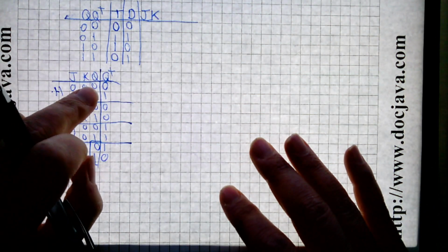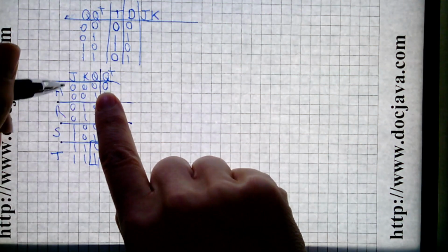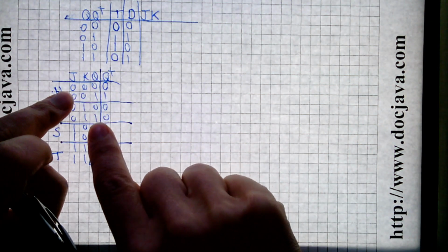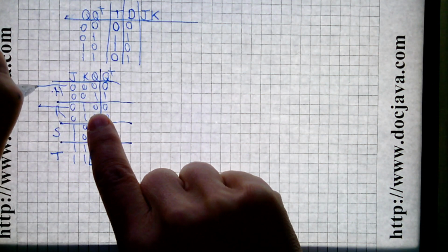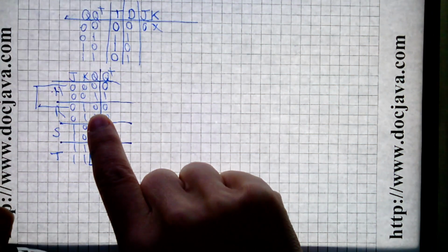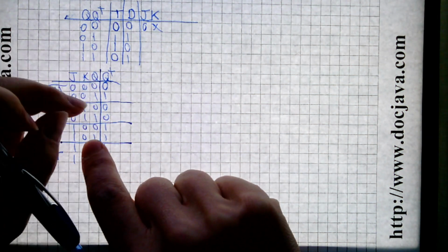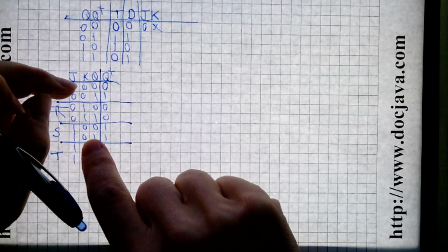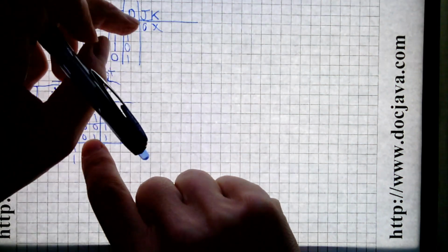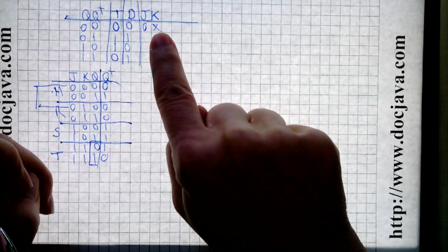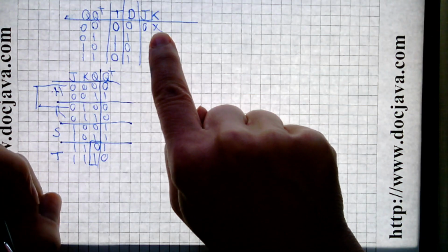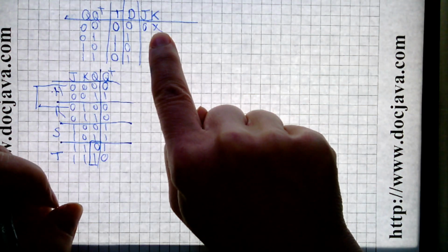We're going back now. If you want to go from 0 to 0, what do I need? Well, I can use 0, 0, or I can use 0, 1. Right, I can do either to get from 0 to 0. As a result, I have 0, don't care. Does everybody kind of see that? There's two ways in which to go from 0 to 0. Because if you're in state 0, you could be in the hold state, and that'll keep you in state 0. Or you could go to the reset state, and that will set you to state 0. So since this can be either a 0 or a 1, we don't care what it is. And those don't cares are going to help us when we do our K-maps.